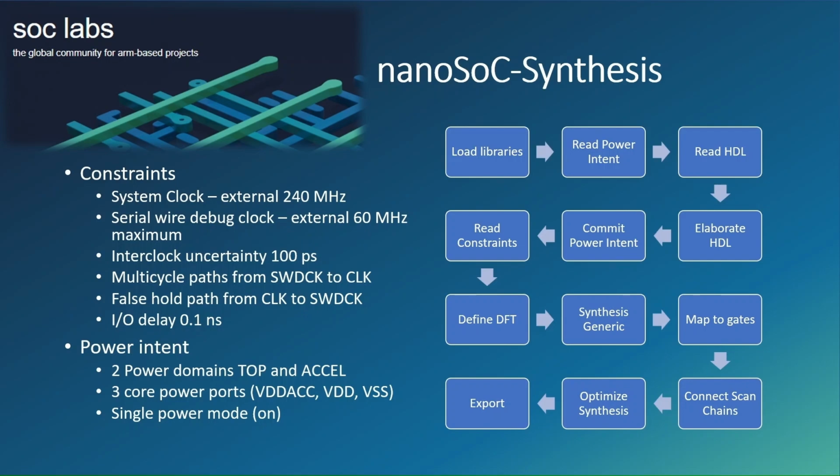What we're going to do in the future is take this so that you can have internal power monitoring for more of the tasks involved at runtime. So particularly things like data movement. We would like to separate it out so that the DMA and maybe the SRAMs are on their own power domain, and you can measure, hopefully at quite high resolution, how much energy you spent moving data, how much energy you spent pre-processing or post-processing data, and then obviously in your accelerator, in your hardware itself.